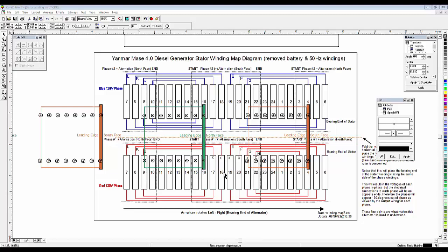Same thing happens down here. It's just the opposite polarity. It's the only difference. I'm sorry, I said that wrong. This generator is so confusing. Up here, these happen with opposite polarities, which made the currents add up. Down here is the exact same thing happening with opposite polarity between these two. Of course, in this case, there's zero current. But what happens here also happens exactly down here too. They are in phase. The blue windings are in phase with the red windings with reference to the armature.